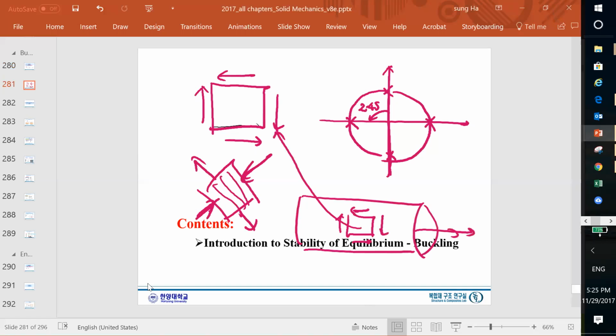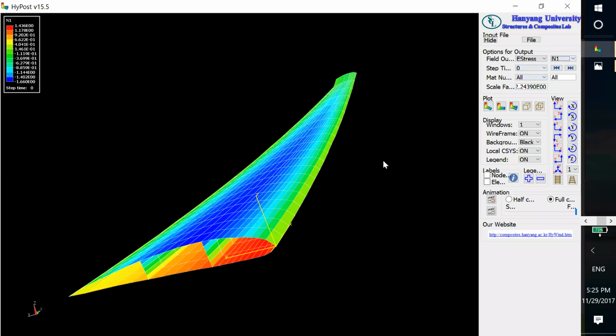And the tool you are using cannot predict buckling behavior. I wish it could, but right now it only gives strengths and natural frequencies and deflection and so on. But keep that in mind, please. We have to consider buckling behavior, especially in compression. Okay?